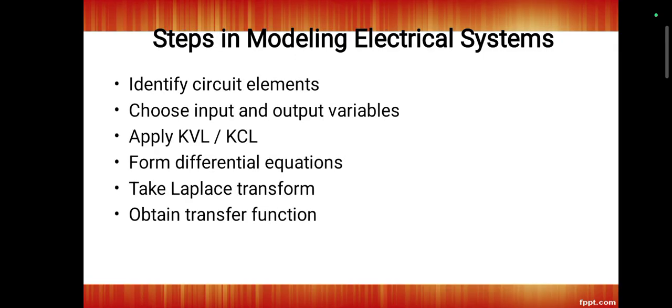Here are the steps for electrical systems. First is identifying the circuit elements, then choosing the output variables. Third is applying Kirchhoff's current law and Kirchhoff's voltage law. Then form the differential equations and take Laplace transforms. Finally, obtain the final function, which is called the transfer function.